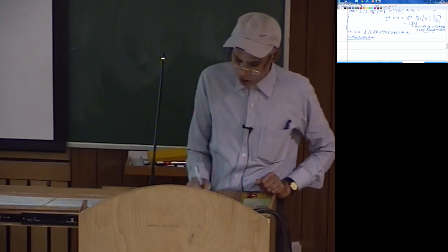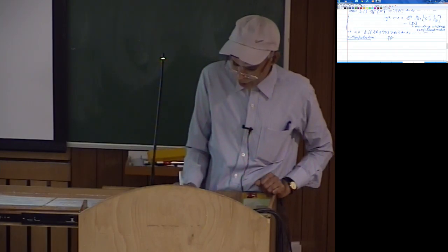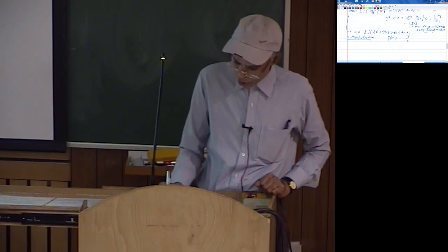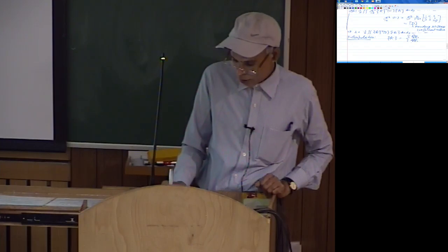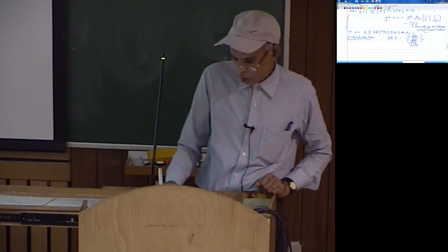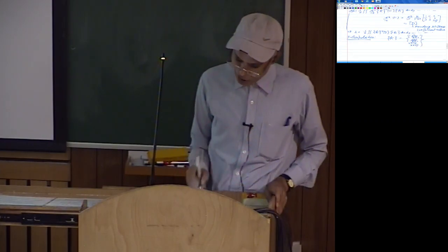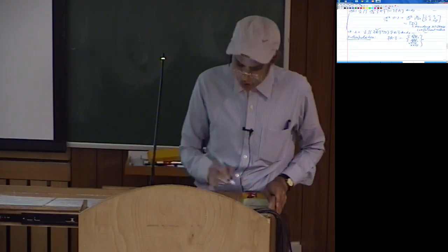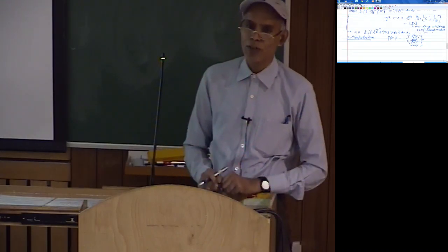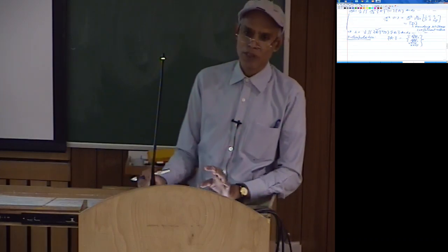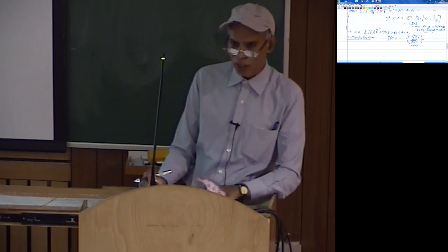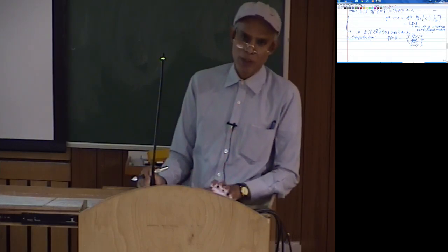Now if I rewrite what we had defined as kappa, kappa was del 2w by del x square, del 2w by del y square, and twice del 2w by del x del y. So this is our kappa. The highest order derivative of w present in the integral functional is now the second derivative. So whatever approximation we assume must be differentiable at least twice. That is from the differentiability requirement of the approximate solution.